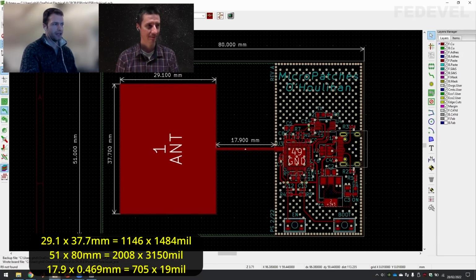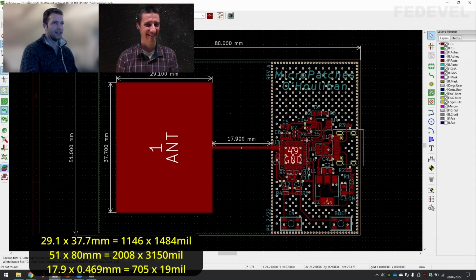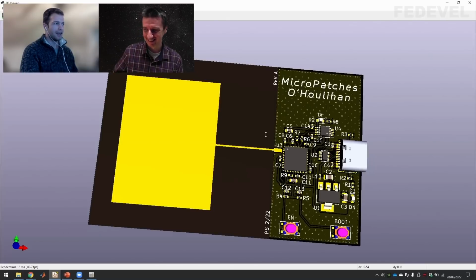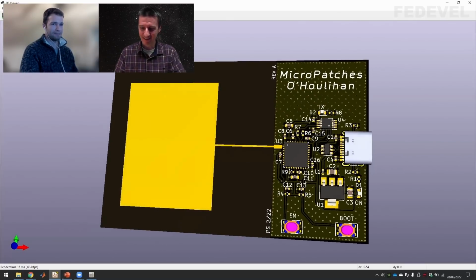That includes tightly fitting all of this essentially digital electronics, doing this quarter wave transformer in this pad. So it's quite long, yeah. It's quite long, 80 millimeters and 50. So it's not the prettiest PCB. But it's 80 millimeters.